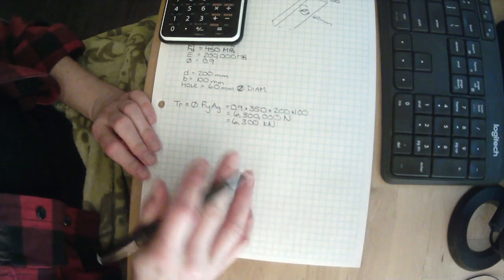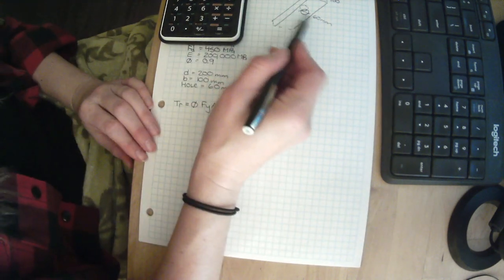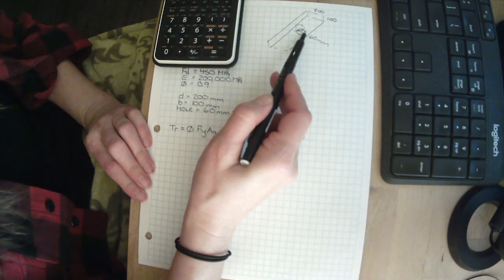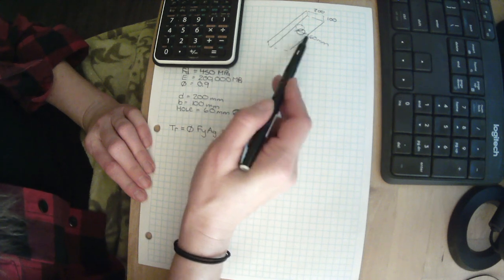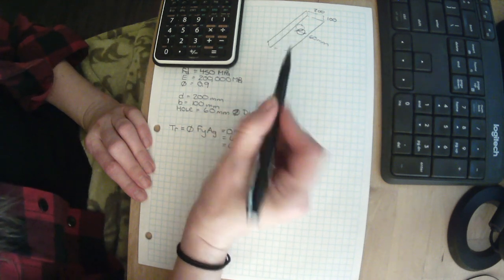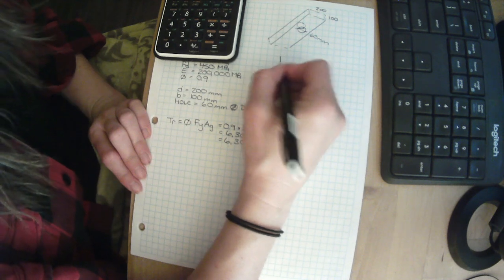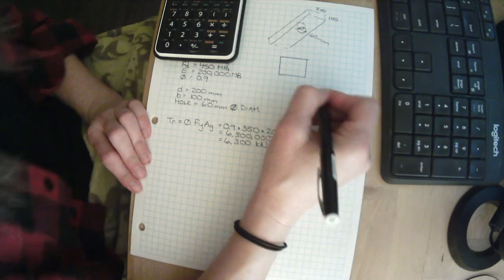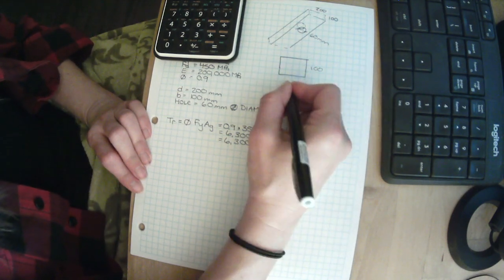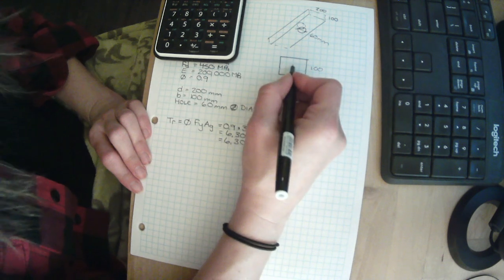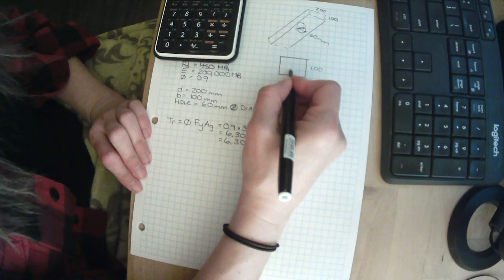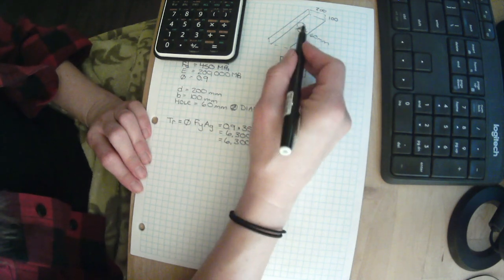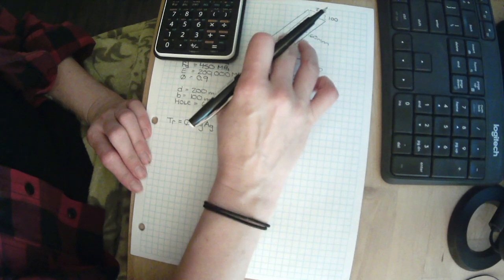Now we also had to check its capacity through that bolt hole. We could check it right here where the hole starts to appear, but we have to check it everywhere across that cross-section of that member. So if this is our normal cross-sectional area, where this is 100 and this is 200, at first the hole opening just starts to appear, and then it gets bigger and bigger, and then it starts to get smaller again as we shift our cross section down the length of this.